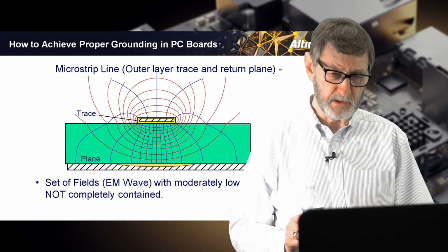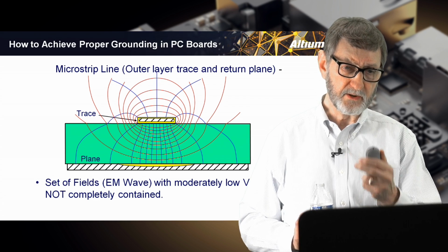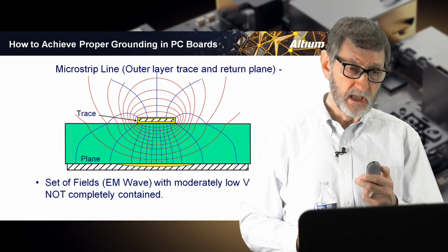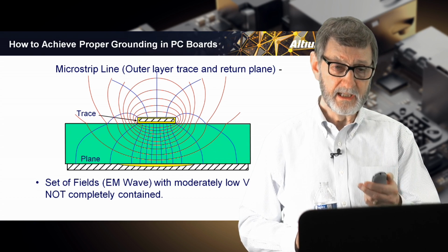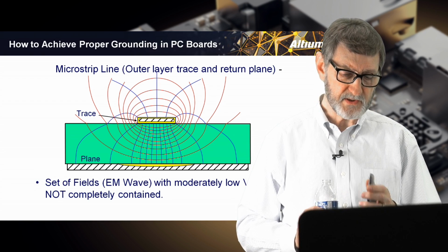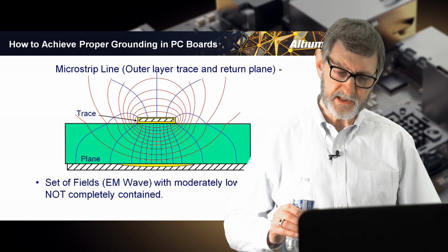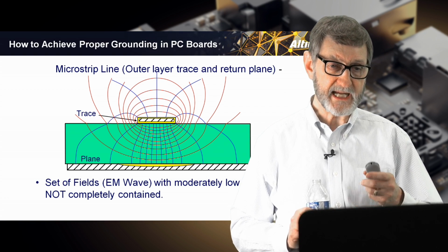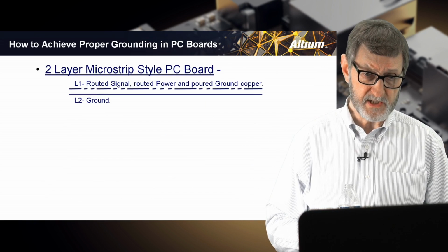Even though the fields will expand more, it makes no sense to drop to a via, go to an inner layer, go a short distance, a quarter of a millimeter across the board, and then go back up through another via to the receiver. That makes no sense at all. So in cases like that, keep short signals on outer layers. It's a much better way to contain and control fields, and we'll talk in a short while about why that statement is true.